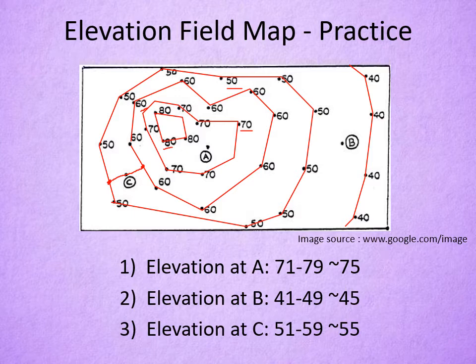Now, the points along this line I drew have different altitude values, because this line is cross-cutting the different altitudes. And we see that C is lying in between the 50 feet and 60 feet height. So we can divide this line in different proportions.